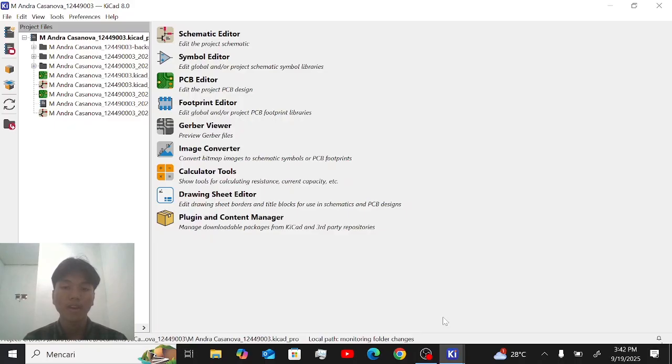Okay. Why is the PCB layout so important? Because proper component placement on the PCB aims to ensure efficient signal flow, minimum interference, and to facilitate assembly and maintenance. Critical components such as IC, sensor, microcontroller, and connector are placed so that signal paths are short, and heat-generating components are kept away from sensitive components. Example: the ESP and IC are not placed close to the regulator.